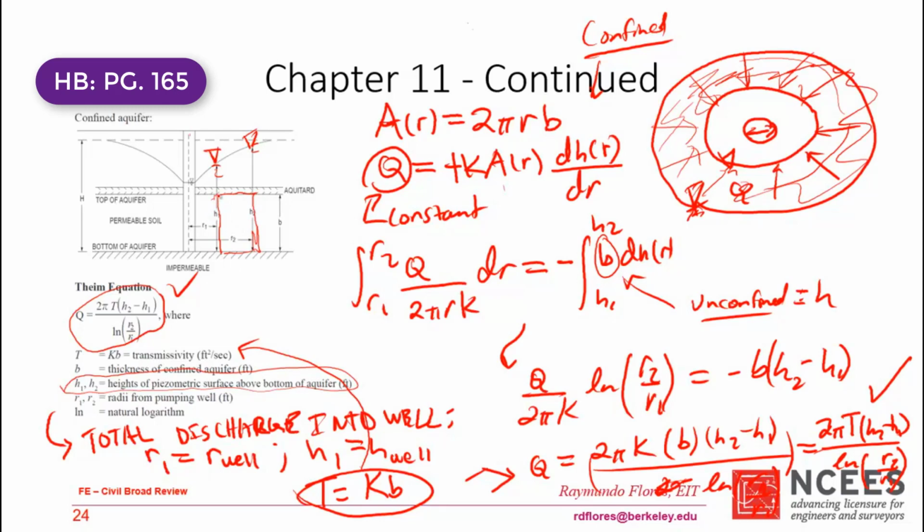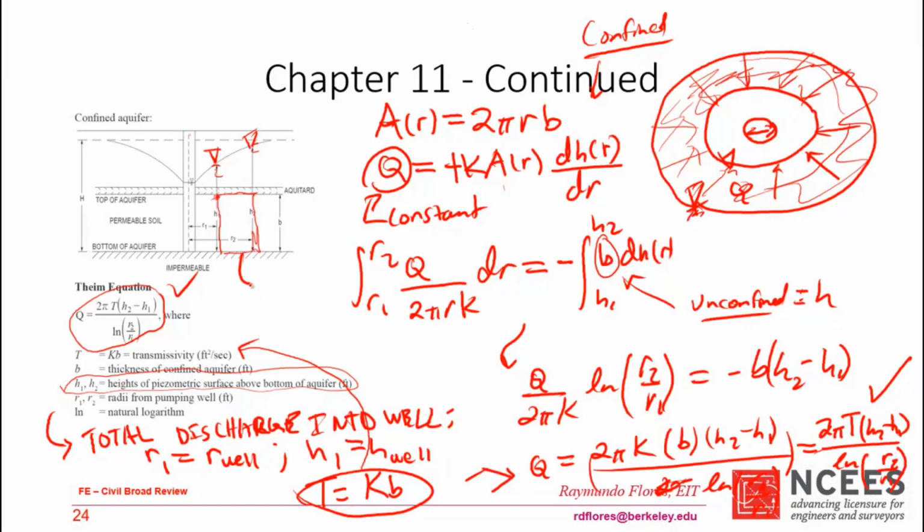We know that at this point and at this point, we know at this point the total head is h1 because the piezometer reading is telling us that. And at point 2, h2, it would have to be this because that's what the piezometer is telling us. So that's basically the case, because it's the total head, it's not the height. It's not the height, it's the total head. So keep that in mind. Let's go ahead and move on. And let me just say Q region.